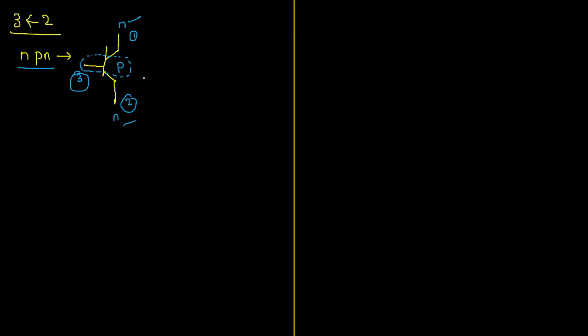In the case of a diode also, we will be having two terminals. One is called anode, another one is called cathode. The current will be directly flowing from anode to cathode. That is what we are calling forward bias. And we all know in reverse bias, the diode will not carry any current ideally, but practically some amount of reverse saturation current will be there, a very small amount of current, approximately equal to 0. If the current is flowing from cathode to anode, we are reversing the direction. That's why that is called reverse bias.